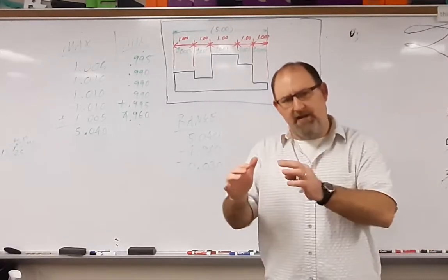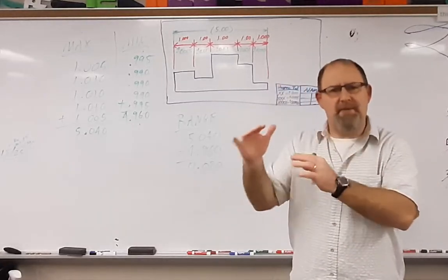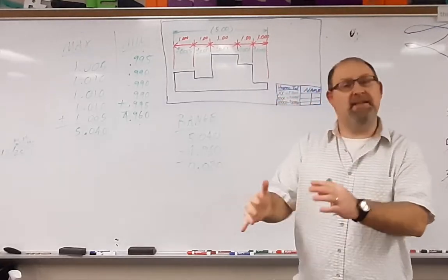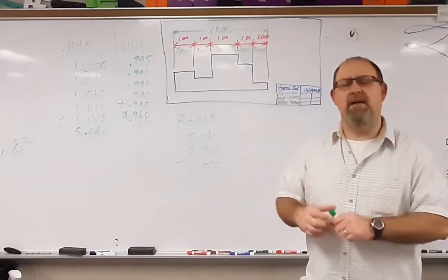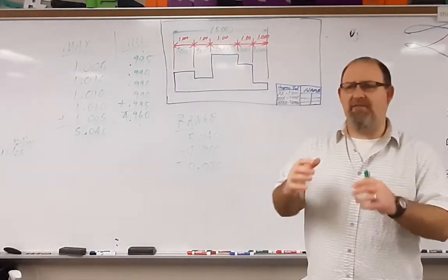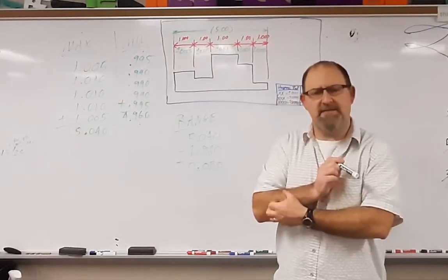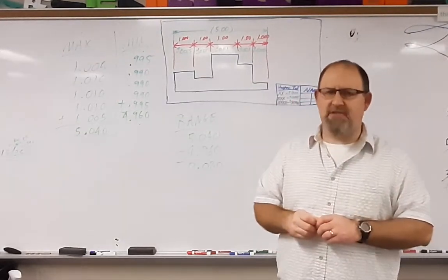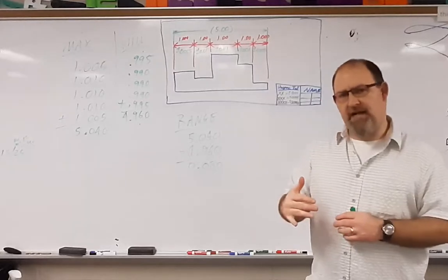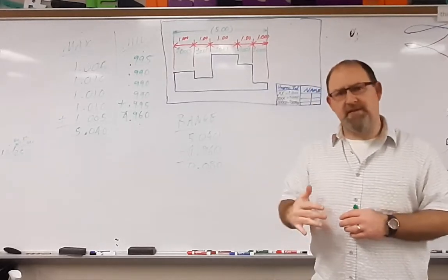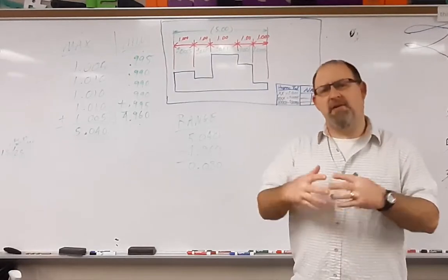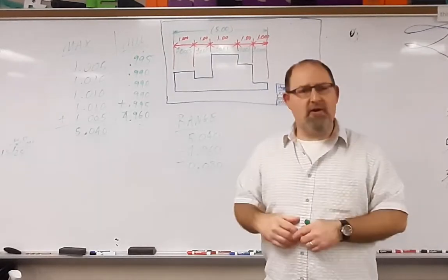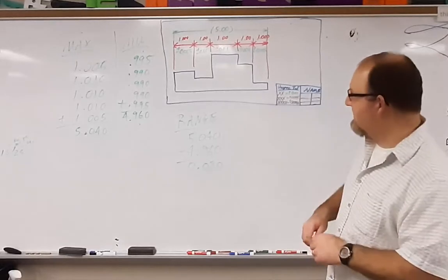You want the tolerances to not be excessively tight unless they need to be. If they need to be, that's fine, then make them excessively tight. But many times you don't have to have super tight tolerances unless it's a very critical application. Most of the time you can have looser tolerances, and remember, the looser the tolerance, the less that it costs, so the cheaper it is to make. But you don't want to have them so loose that it causes malfunctions and the parts to break.